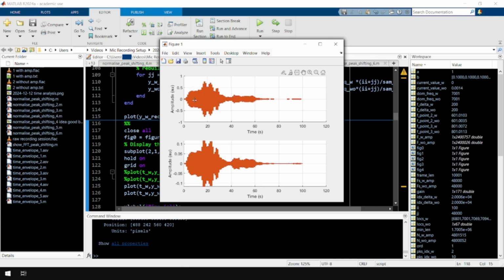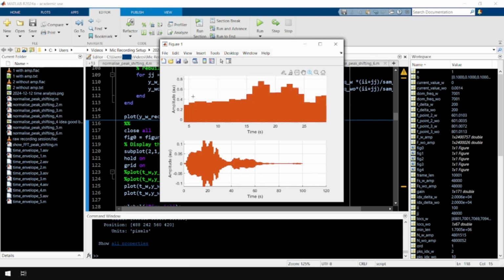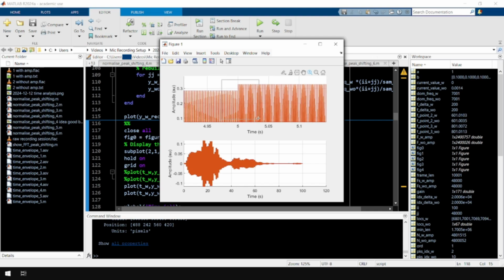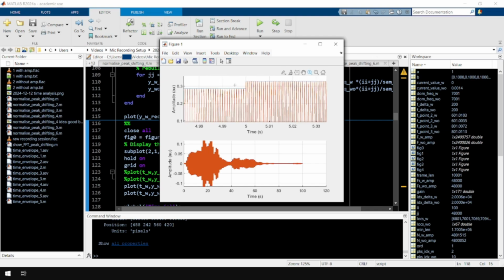And what that looks like is this. So you can see that there are no longer those strange transient spikes, and these are all kind of moving in discrete steps, which is what we had at the beginning, but in a more sort of idealized form. This is a reconstructed wave. You can see there that it is just the sinusoids, and they change amplitude and frequency, matching this smoothed envelope function, smoothed and discretized.